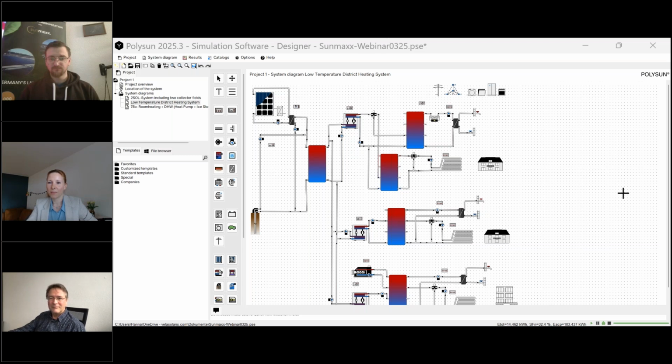You cannot directly set it for sure, but you can pre-simulate the system. So you can start the simulation on the 1st of October, or the 1st of June in the previous year. It will count down the days and simulate the system during this time, so that the thermal energy storage has a different temperature than if you start on the 1st of January. And we really recommend that, especially if you want to design seasonal storages, like an ice storage, for instance. Thank you very much.